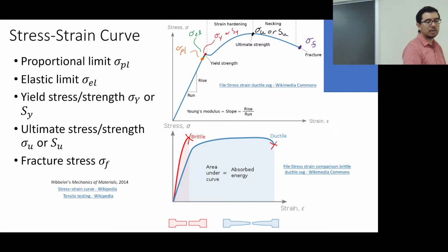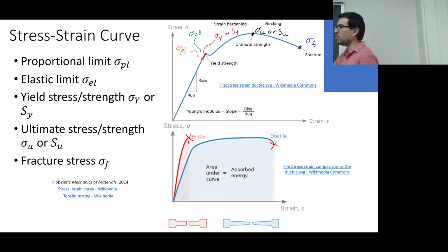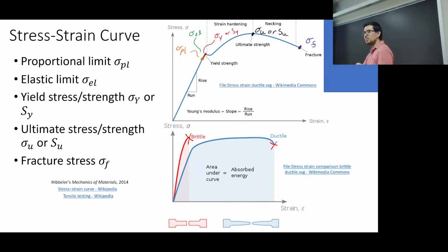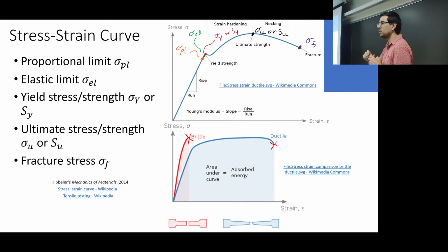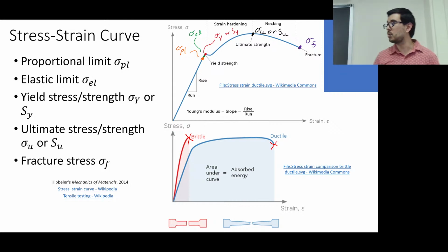Similar type of principle here. Usually though with springs, we never say we're breaking them or we're making them yield. You'll do that in DMC as well though, actually. You'll look at some calculations for coils, and it turns out that the shear stress is what is the problem.